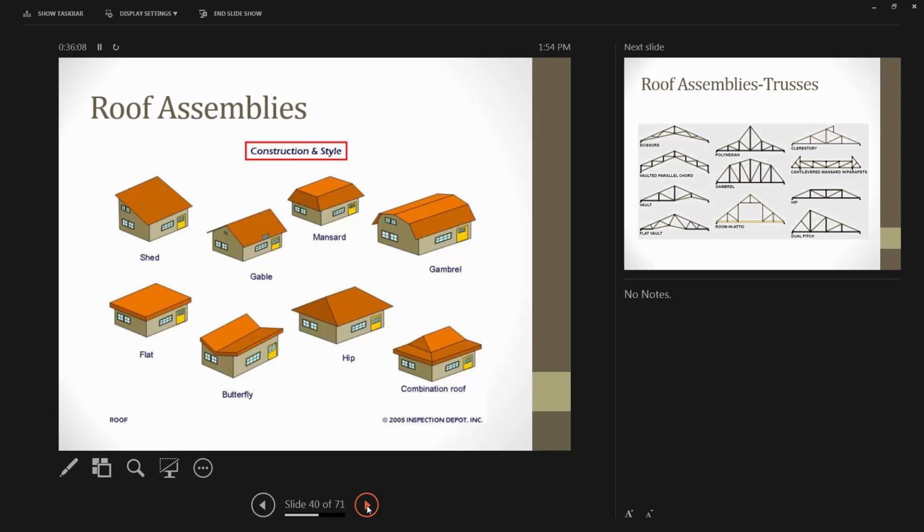We'll talk a little bit more about different types of roofs, and you've probably all seen these different types of roof somewhere or another. And what becomes interesting in design is they all have their pluses and minuses when it comes to moisture protection, thermal protection. Some are far easier to seal than others. Some are far more effective. I'll talk about venting in just a minute. And they can have a pretty big impact on your thermal performance and on your overall energy performance.